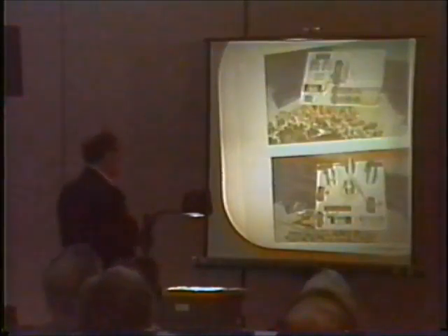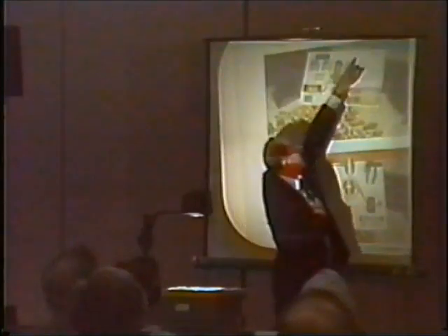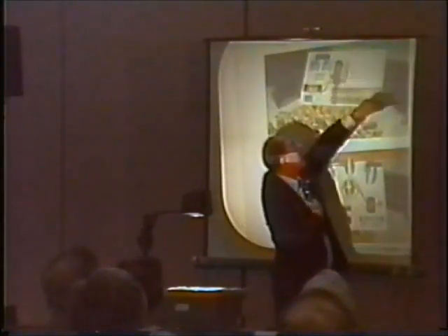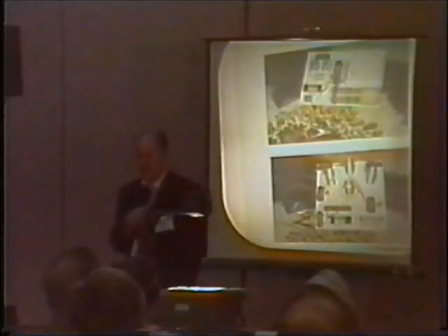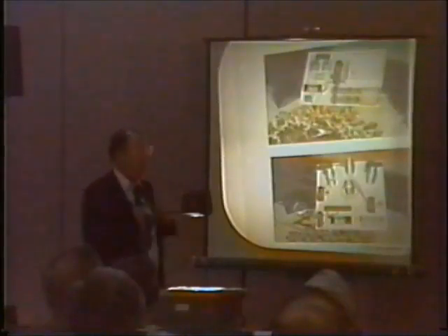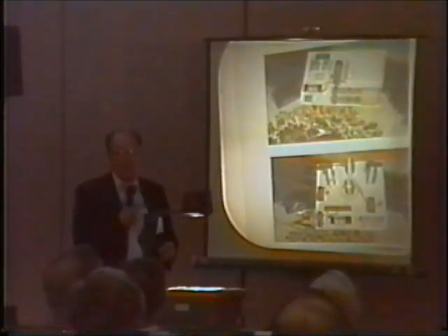And coming out, what you're interested in here is going to be your plus DC, and this is going to be your minus DC. These are your two AC inputs going into the diode bridge. At this point, this particular one is set up so that you get 60 cycles at a usable level where you can just plug directly into it and you're off running.